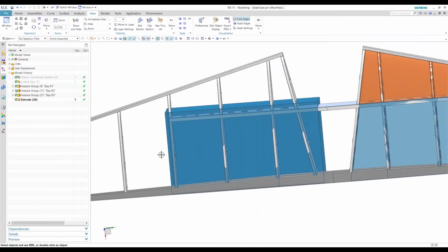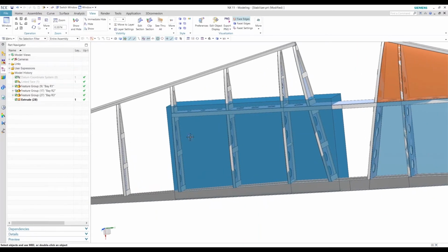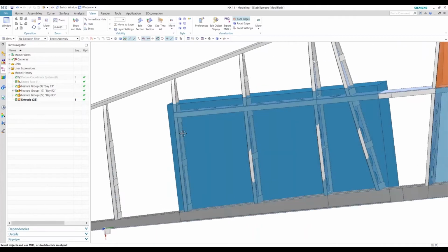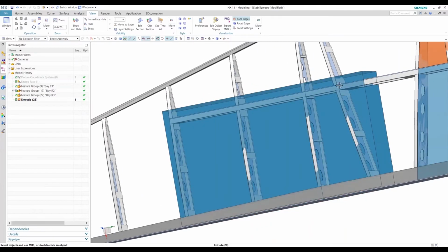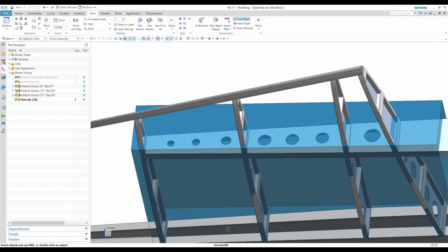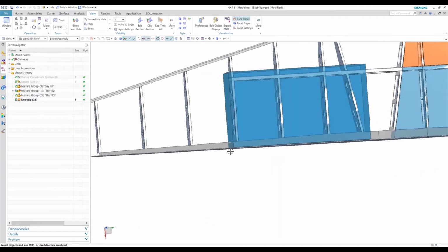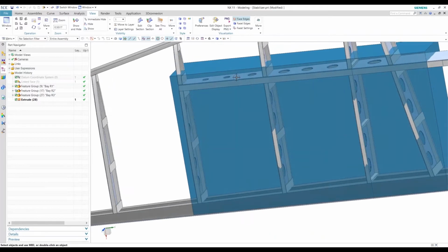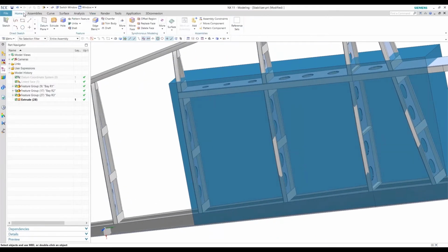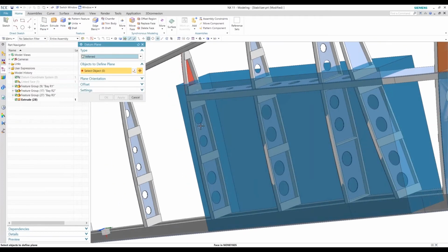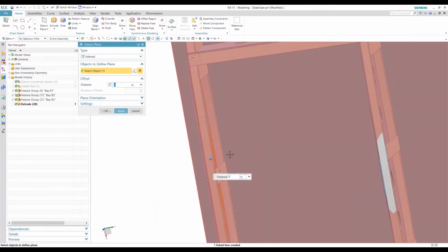Okay, so now the next step here is to start creating planes along the sides here. So we have a plane which we started on this aft spar. So we'll want to create some on these ribs here. So I'll go to my home tab and start creating my datum planes. And we'll use those planes again to trim. So I'm holding here and selecting this interface.